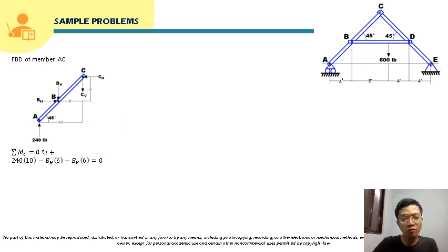Okay, and also for BH, its moment arm will be this distance. So from the figure, this side is actually 8 plus 4, so this is 12. So its midspan is 12 divided by 2, so that will be 6. So this side will be 6. Since this is 45 degrees, if we put a line here, that will be the opposite side of this triangle. So this will be the adjacent and this will be the opposite side.